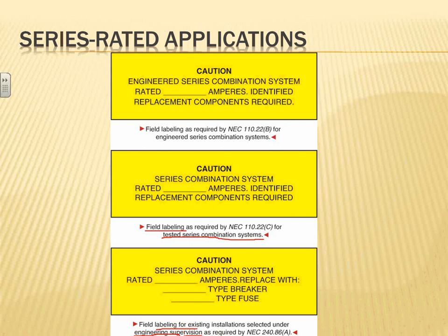So the point is, if you have a series rated system, you must have a label similar to this one to identify it's series rated, and what type of replacement you need. Any comments, guys, about series rated equipment?